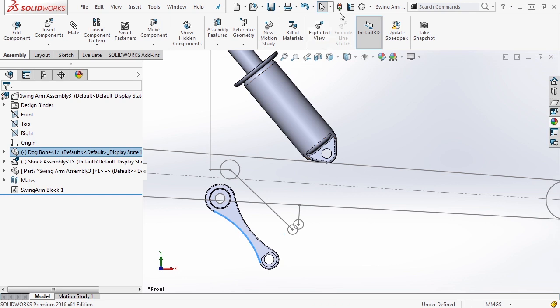So this is a very dangerous methodology because if we're creating a linkage that's supposed to be rigid between this point and this point, obviously it gets real tricky if you start relating to that geometry. So this is one of the very big downfalls that I see new users make when they start creating these components in an assembly. I highly recommend that you start by creating your individual part files as a multi-body or as their own individual part files, bring them into the assembly and then modify their geometry. So that way you don't accidentally fall into these pitfalls.